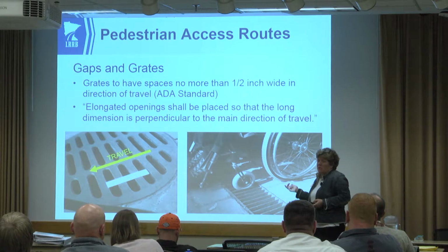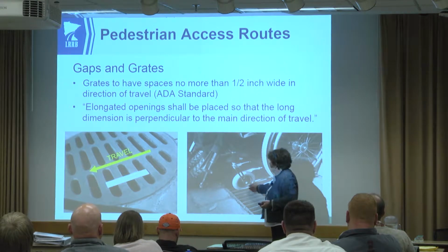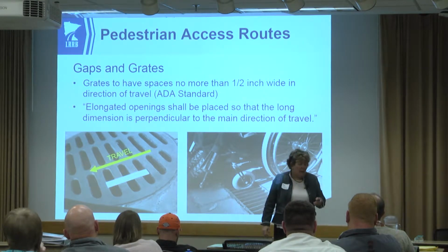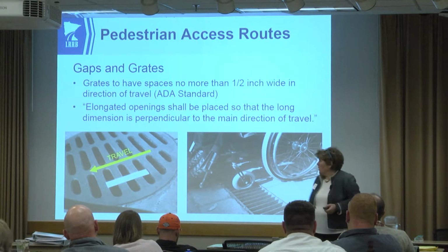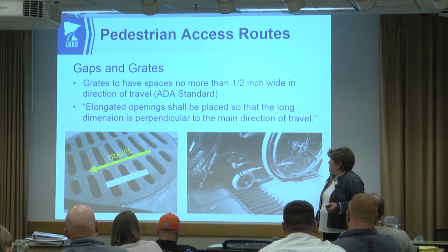There's other standards that you can pick from for approved castings. Here's an example of how the wheelchair can get caught in there. So there's many situations where the grate selection has impact on the pedestrian access route.